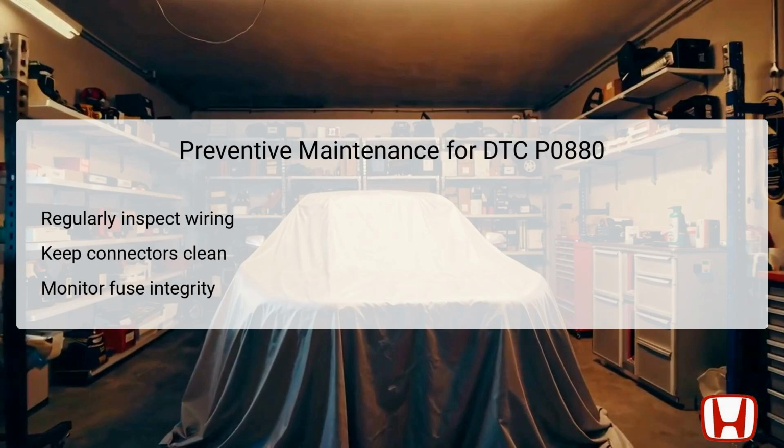Monitoring the integrity of fuses related to the TCM ensures that the circuit remains protected from overcurrent situations, preventing premature failure. Additionally, periodic scans of the vehicle's diagnostics with the HDS can help identify error codes or early warning signs of electrical issues. These proactive steps contribute to the longevity of the vehicle's transmission system and enhance overall reliability.